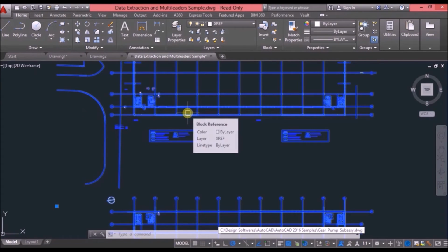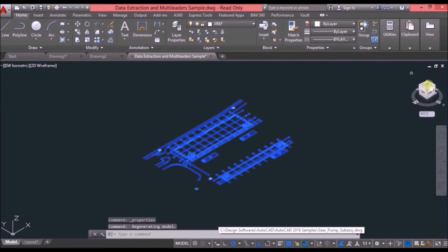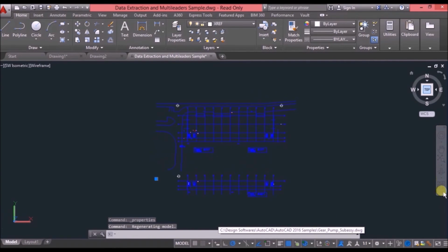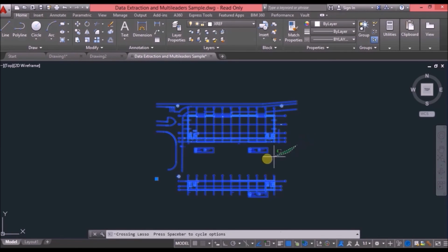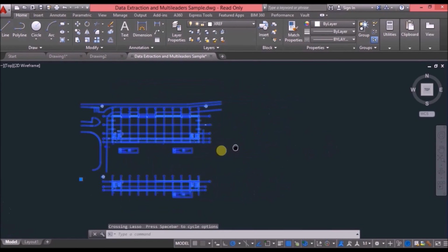Okay, so this was the overall layout. Also, this is a steering wheel. Basically this will be used only for 3D drawings because it will show you different views of the 3D layout, which will not be used in 2D but will always be helpful in 3D. Similarly, this is a navigation bar used for rotating and panning. Rotating means you just rotate the object in all the axes you want. Panning is like moving an object in the same plane but in a different direction. This is called panning. We'll see that later.